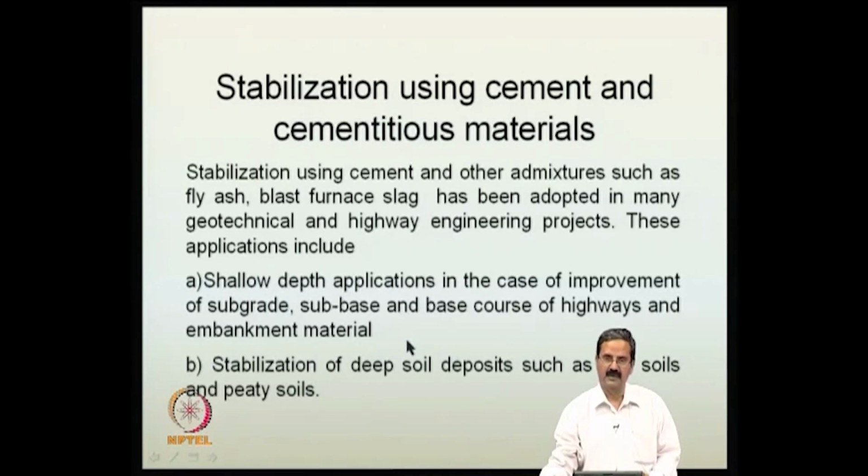The other important point was that there are some places where the soft soil is so deep and very soft, and you need to construct something like containment areas or some sort of big structures. So, you must stabilize deep soil deposits, maybe up to 10 meters. Like we have seen many other techniques, like prefabricated vertical drains, then stone columns and all that. This is also one of the techniques.